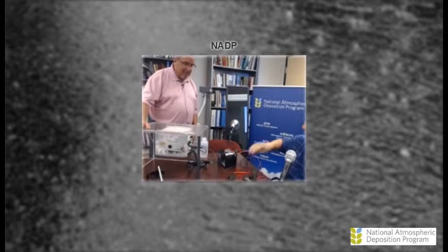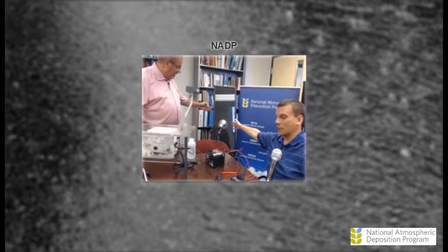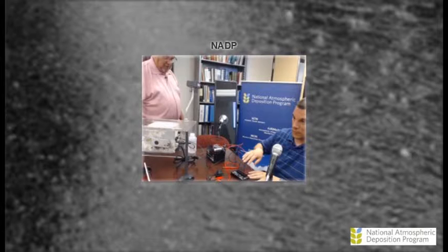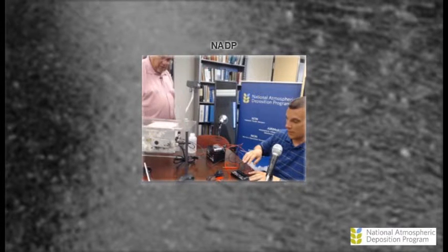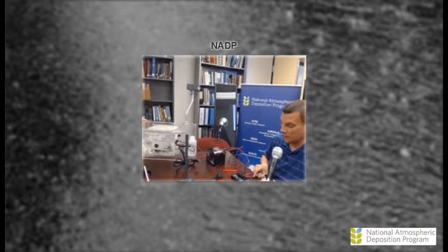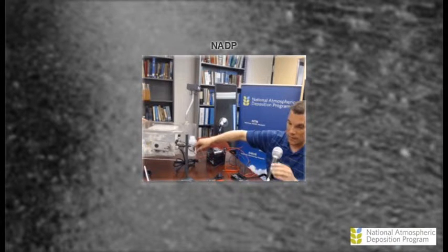So behind us, we have a solar panel here. We've got a little sunbeam we'll turn on in a minute that's simulating sunlight. It's wired into our charge controller here, and we'll have a close-up of it in a minute to show the different connections. That has multiple leads: there's the solar panel input lead, there's a connection to our 12-volt battery, and then a separate connection to what's called the load on the solar controller, which powers the actual collector.